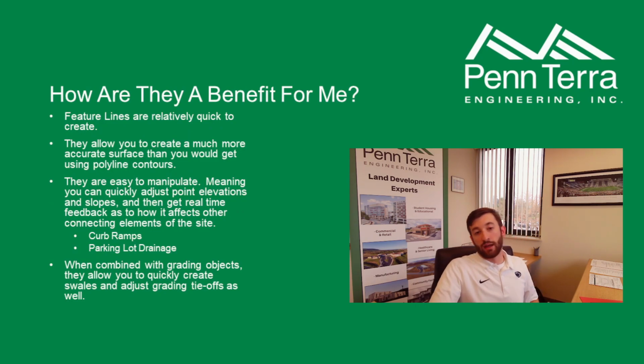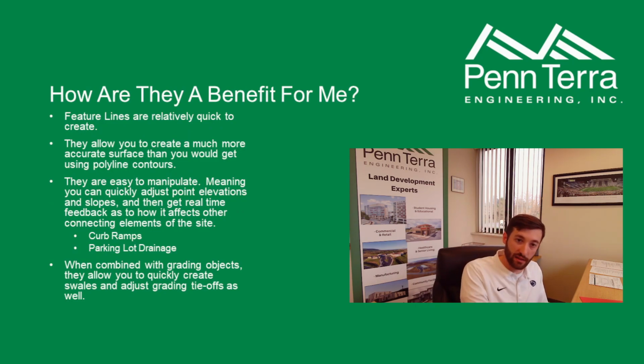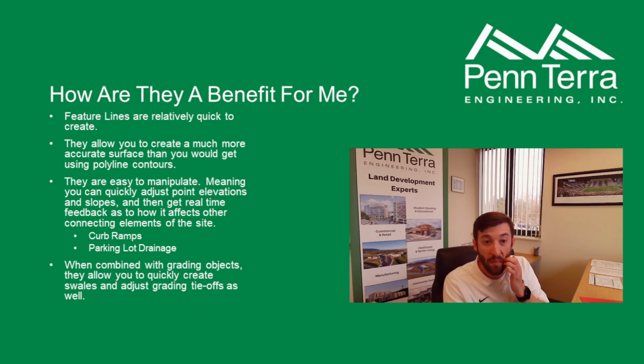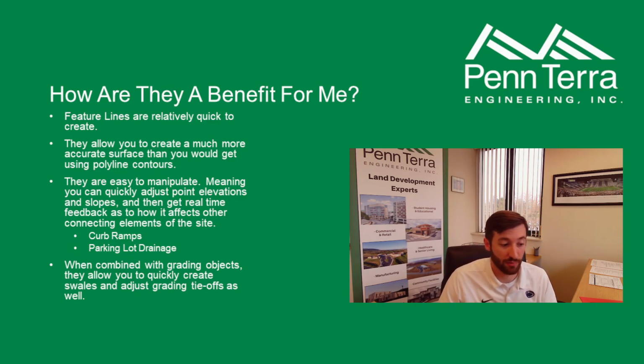Okay, how do feature lines benefit me? Feature lines are pretty easy to make. They're pretty easy to modify. They take a little bit of time to create, but once you have them, if you need to make tweaks, it's much, much quicker than manually calculating points and labeling them. It can also make your surface much more accurate for slope labeling, for earthwork calculations.